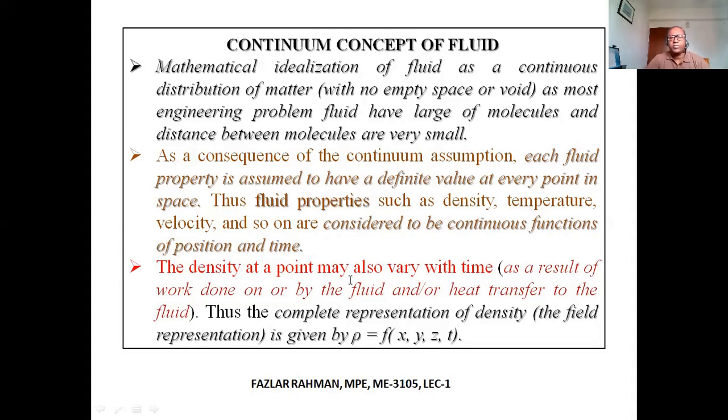Density at a point may also vary with time as a result of work done by the fluid or heat transfer to the fluid. Thus, the complete representation of density in a fluid field will be given by rho equal to a function of x, y, z, and t.